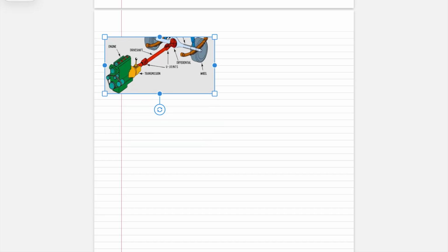What is that? So if you have, for example, in this automotive case, an engine and a drive shaft, which is transmitting power from the engine, which is in front, to the rear wheels. So now this drive shaft is experiencing torque that is being generated by the engine, and that torque has to be transmitted by the shaft to the rear differential, which will then provide the torque to the wheels, right?